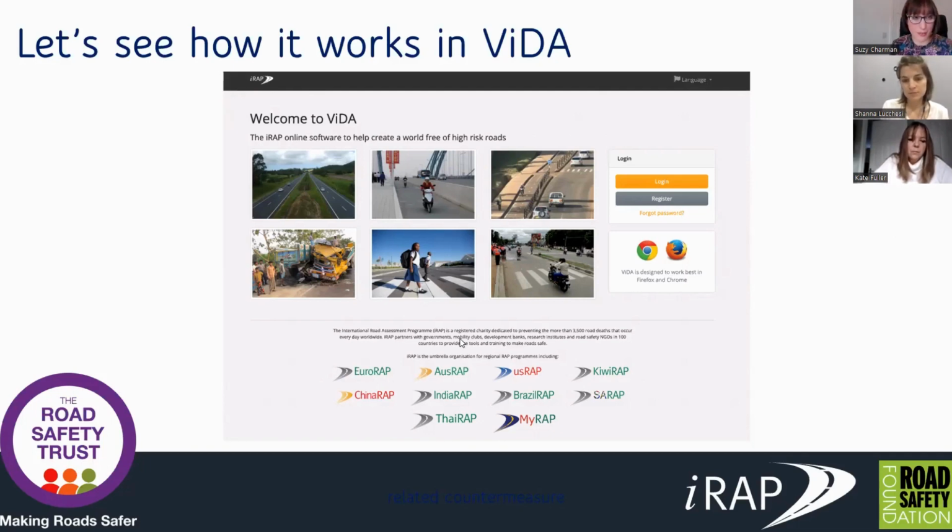Nigel's also asked what's the criteria for rural versus urban. Kate, have you managed to find it? Hi, yes, I've got this, thank you. So it is in the coding manual, and urban is defined as a development spanning at least 400 metres along the road. Small isolated settlements of less than 400 metres may be coded as changes to land use where there are sites of high intensity activity. And then rural is an area outside of an urban area or rural town or village, or where roadside development does not impact the road, or where it's separated by a large fence or wall. So it's quite specific in the coding manual.